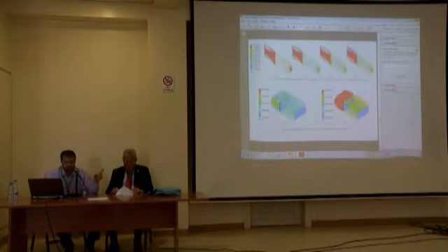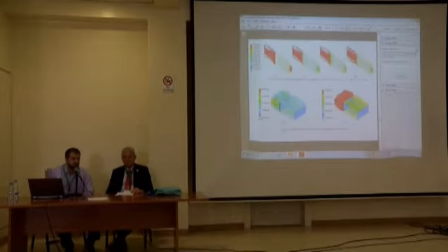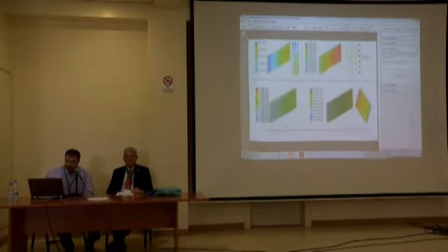Here, for example, you see some recirculations at the extremities of the coil, so you might have an opportunity to eliminate these, maybe through modifying the geometry of the coil. So once you have this information, it will be important. The last figure here shows the refrigerant zone streamlines.